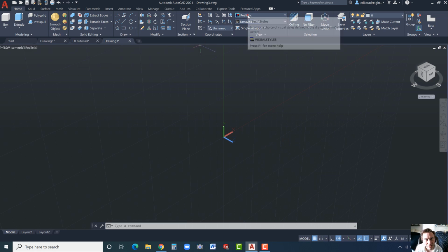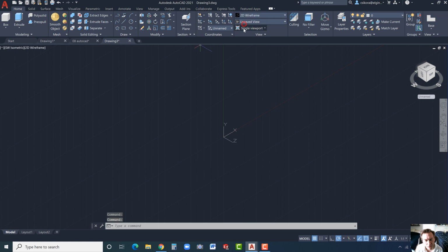Let's go, and I like to start off with Wireframe, and we're going to go to the line tool here, and now turn on the snap, and get to that origin. Click and drag across here, and make it 2.5. And then hit escape and hit enter again. Snap to that point, drag it down, and just make this 2. If you can snap to it, that's fine. Oh, and enter again. Forgot to click. So get to 2 and click, and then hit escape.